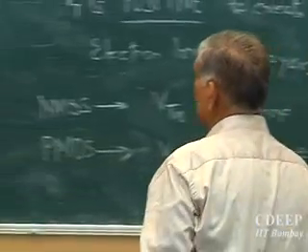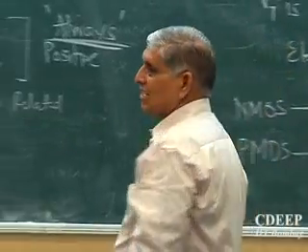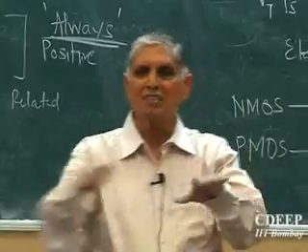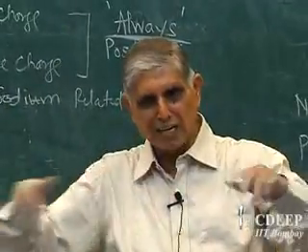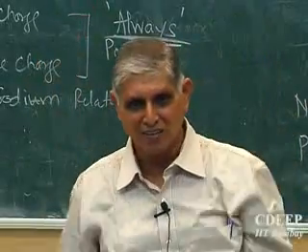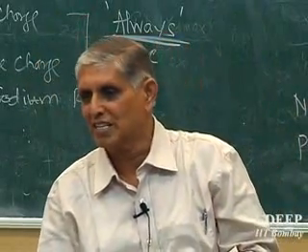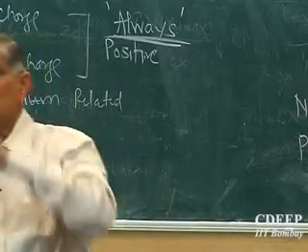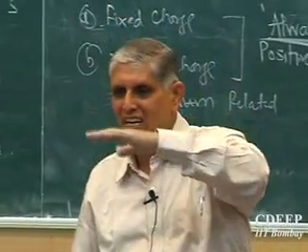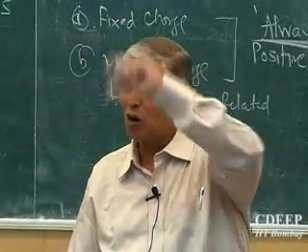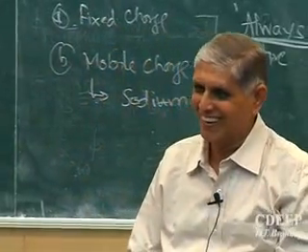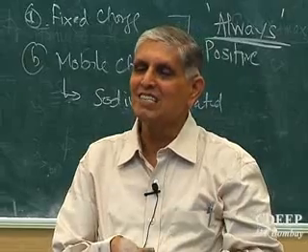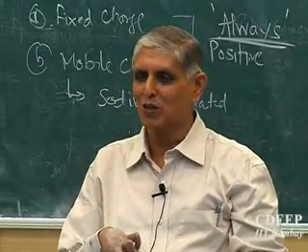थोड़ा chemistry सोचोगे तो पता लग सकता है. Silicon, on the top of the silicon surface, the bonds are open. जितने सिलिकॉन एटम्स होंगे उसका ऊपर का बॉन्ड तो है नहीं, बिकॉज वो एयर है, उसको बोलते हैं सरफेस स्टेट्स. ओके. नाउ दीज सरफेस स्टेट्स, if I put oxide, most of these bonds will be satisfied. Okay, but some may not. Okay, so it's called trivalent silicon is left there, which is positive charge.